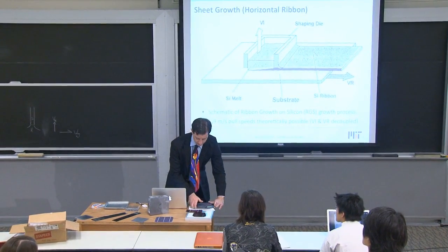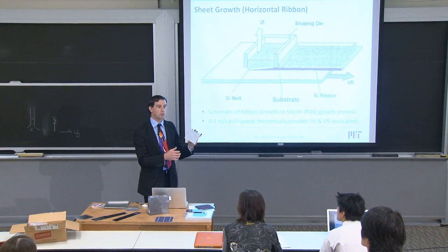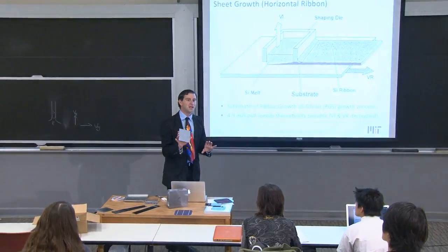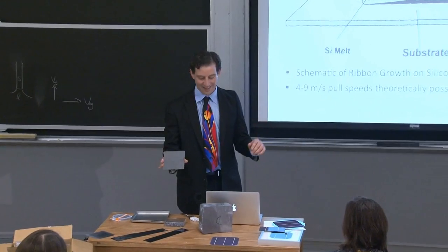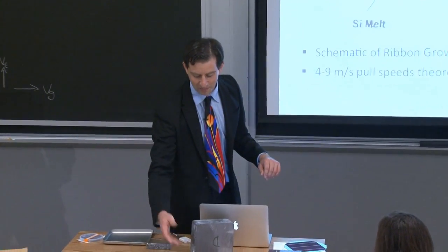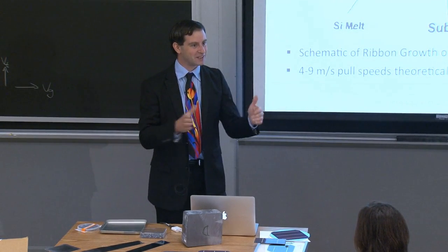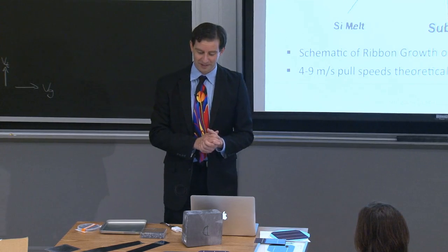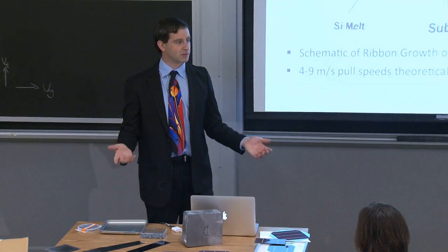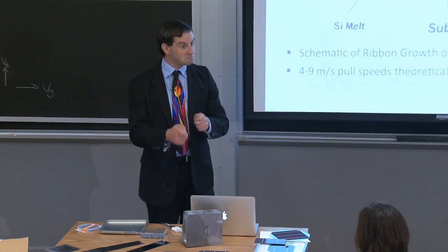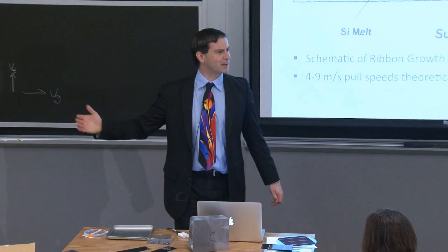And you can already see that these wafers that I have up here are a bit small. These were the previous generation size. I believe these are 12.5 by 12.5 centimeter squared. Most laboratory devices that you and your colleagues will manufacture are on the order of 1 by 1 centimeter or smaller because of a variety of factors. One is the transparent conducting oxide, as we solved in our homework problem. We're limited in how big we can make the device by the sheet resistance of that transparent conducting oxide. Another problem that we typically run into is just that we're not able to deposit uniformly over a large area. We don't have the deposition equipment for it in our labs. We're trying to optimize a new material, and we don't necessarily worry about making module-sized devices out of it.